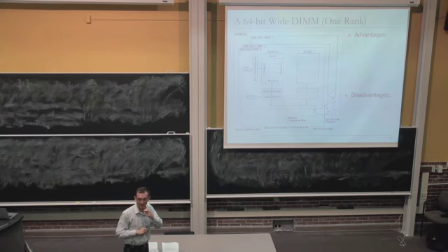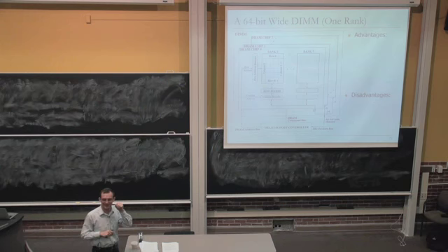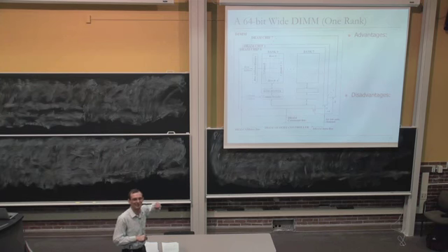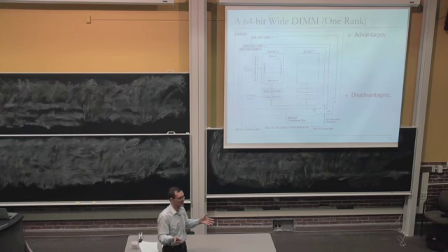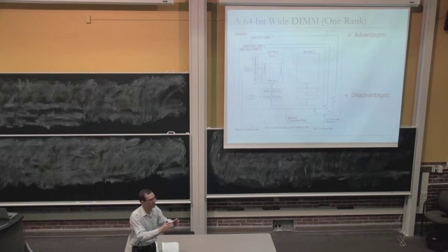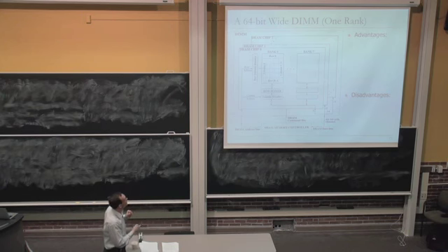Yes? Is it useful to divide ranks between several modules, or does it not matter? Why would you want to do that? I don't know. Is there any advantage to having 8 ranks in one module, for instance, or 4 ranks in one DIMM and another 4 ranks in another, having 2 modules? Oh, yeah, you could have 2 modules. We'll get to this. We'll build up. You could have multiple modules to increase capacity. Let's say you want to build a DRAM system that has 1 terabyte memory, right? You cannot have everything in one chip because of latency. I mean, you could build it, but that would not be cost effective from the DRAM manufacturer's perspective.